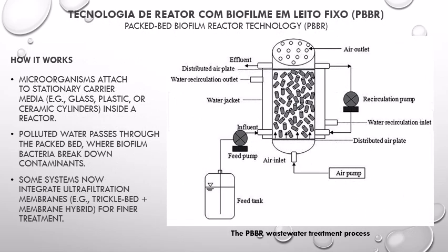The next which we do have is the packed bed biofilm reactor technology, the PBBR. How this works is the packed bed biofilm reactor technology uses stationary carrier media, just like plastic or ceramic pieces, coated with bacteria to treat wastewater as it flows through the system. Now, some advanced versions actually combine this with ultrafiltration membranes for even cleaner results.